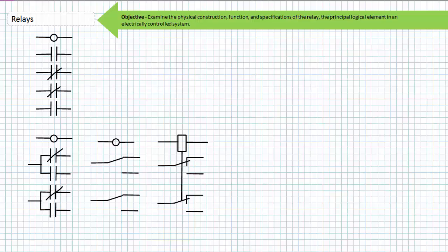A thick, tangled jungle of not only NEMA and IEC differences, but also manufacturer-specific pin numbers and idiosyncrasies exist, especially for older relays. This being said, most manufacturers now offer dual NEMA and IEC numbering schemes, with the IEC numbering scheme becoming more and more accepted because of its standardization and ease of interpretation.